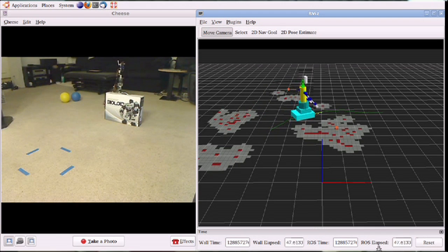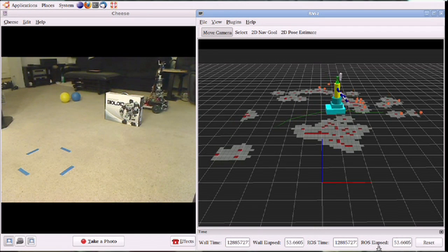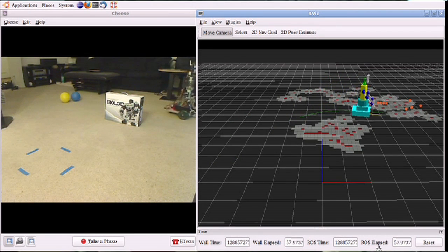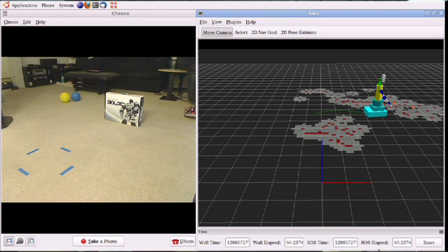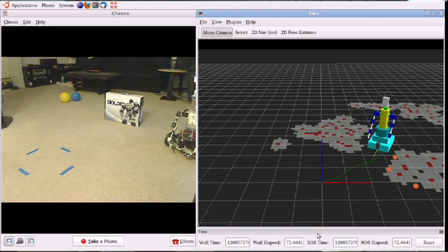I say, come all the way back around here. But then ROS and the path planner has to figure out how to do that without running into the obstacles that it's already recorded. And again, that's something you get for free. The planner is doing some kind of a wavefront analysis or something of that nature, and it gets itself around the obstacles. And as it goes, of course, it updates the occupancy map as the panning IR scanner picks up more objects.